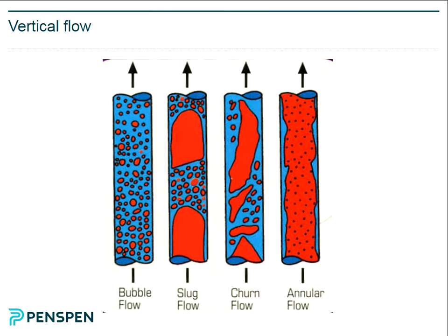The other type of two-phase flow worth talking about is the terrain effect with pipelines. If your oil is not completely dead, it's still got some gas dissolved in it, and it will have a vapor pressure which is above ambient. This is a pipeline. This is height in meters. This is distance. So this is effectively a pipeline going over a mountain.